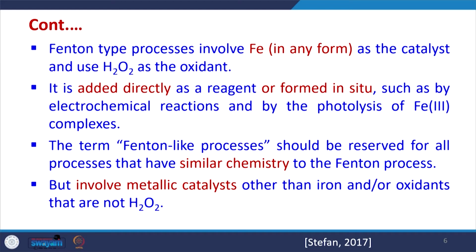Now, Fenton-type processes involve iron in any form as a catalyst and use H2O2 as an oxidant. This H2O2 can be added directly as a reagent, or it may be formed in situ as well, such as by electrochemical reaction or by the photolysis of Fe3+ complexes.